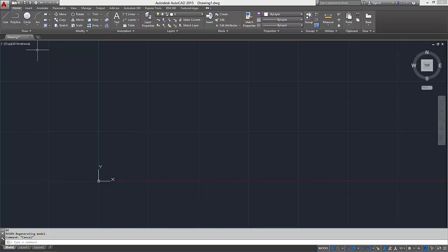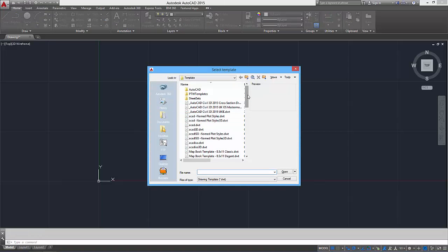This is the quick access toolbar, so things like create a new document, and as we're on create a new document, if we just look at this, the default document that we want to use is the AutoCAD ISO DWT. A DWT is a DWG template. So a DWG is an AutoCAD drawing. A DWT is an AutoCAD template, which when you launch will turn into an AutoCAD drawing. So AutoCAD ISO DWT. That's not the one we want to use. Some people use that. This is the Imperial template, which means that there's a different scale factor going on regards to the units and the paper.